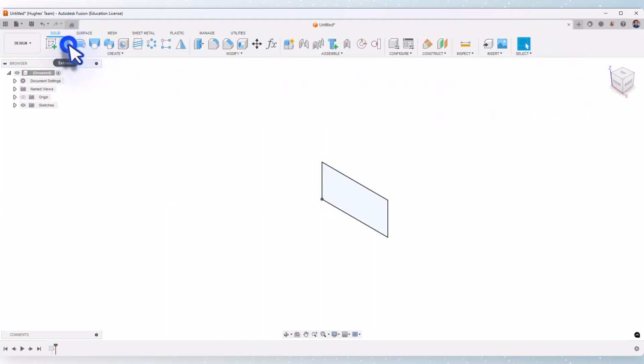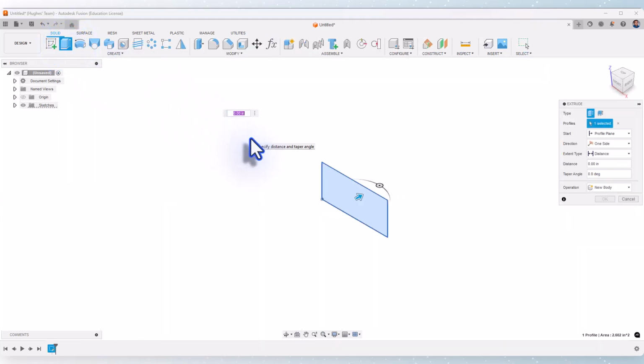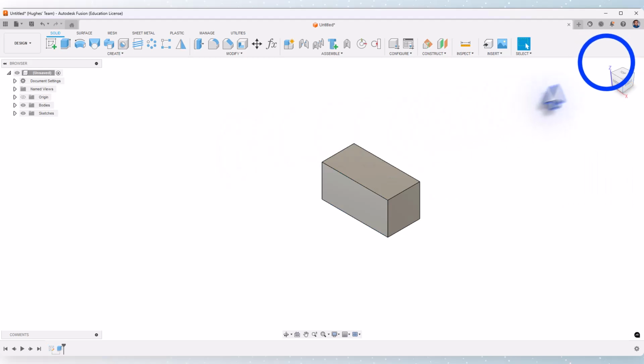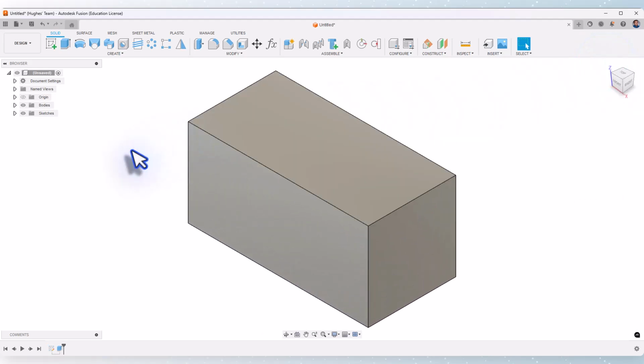And I'm going to go ahead and extrude, and this extrusion depth is going to be 1 1/8. Hit enter to set that in. So we're going to start off with kind of like a rectangular prism that's been lying down. And what we're going to have to do is create the little cutout opening from the front face. So I'm going to select create sketch one more time.